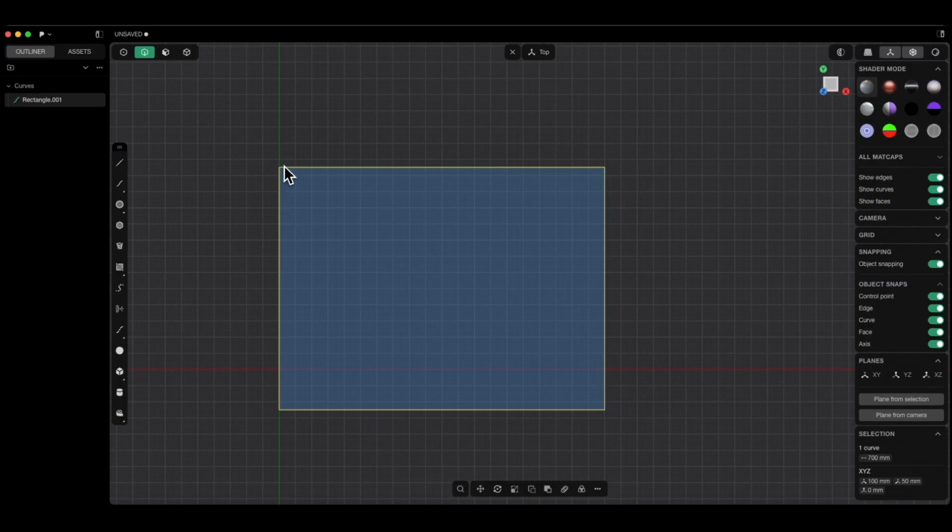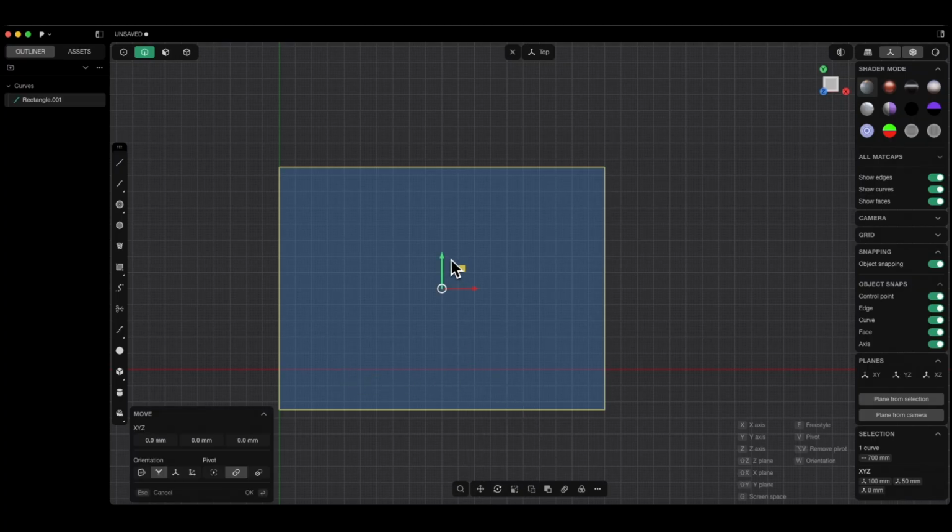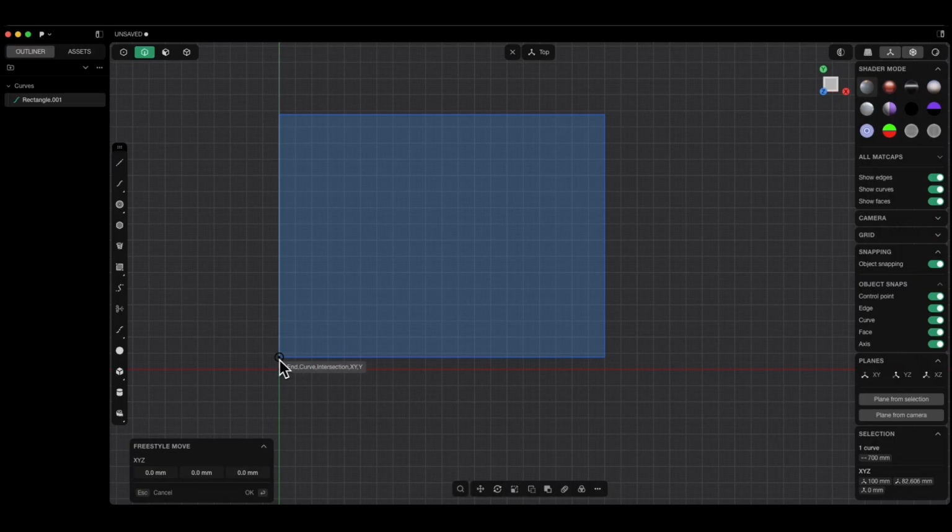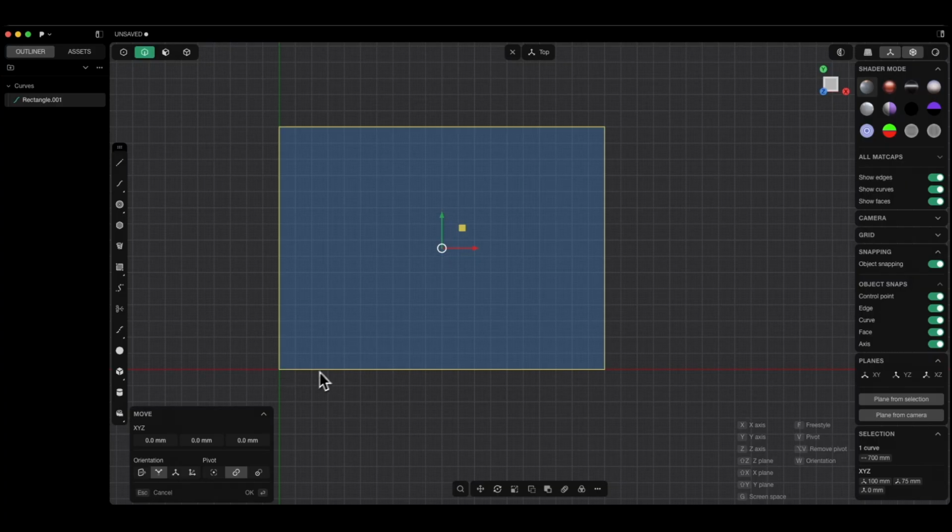And if you want to move this geometry so that the corner of the rectangle lies exactly at the origin, we can do it easily with the move command. Here you can shift it along the y-axis by entering a specific value, but to do this precisely, we must enter the exact value in this field. In this example, we happen to know the offset value, but sometimes you won't know it. That's when we can use the freestyle option. Press the F key on the keyboard, then select a reference point, select this corner, and then select the target point to which we want to move the geometry. I'll show you again how this works.